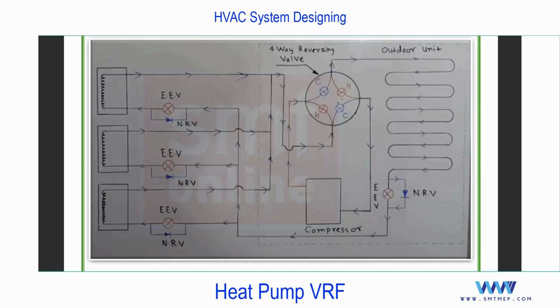So now you see, in heating mode, this valve and this valve are in closed position, and this one is going to be in open position. The cycle starts from the compressor only. You see the refrigerant, compressed with high temperature and pressure, goes through this line and reaches up to this point. After this point, this valve is closed, so it will enter through this valve to this line, and this valve is also closed.